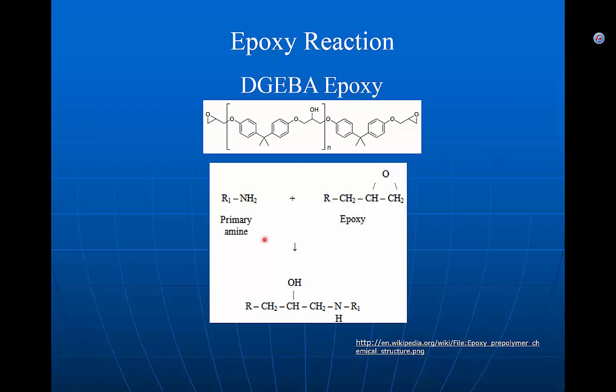Okay, so the epoxy that you probably bought at the hardware store is usually cured with an amine of some type, some primary amine. Or it might be a primary and a secondary amine. We'll just look at the primary amine as our model. A secondary amine is going to have the nitrogen in the middle of the molecule, and so it's just an NH, not an NH2, but the basic mechanism is similar. So R simply means I've got some organic molecule hanging off. Same thing here, I've got some organic molecule, probably some version of a bisphenol. And then there's the oxirane group, which is this little functional group on the end.